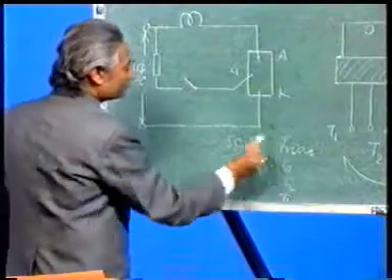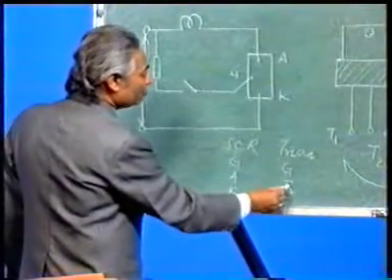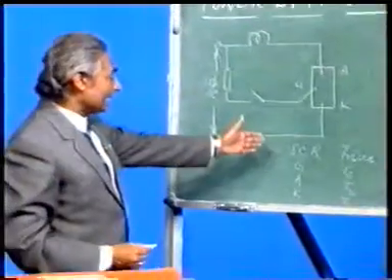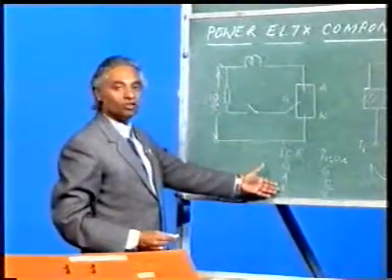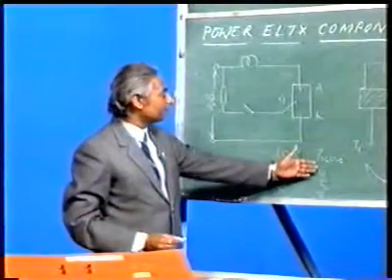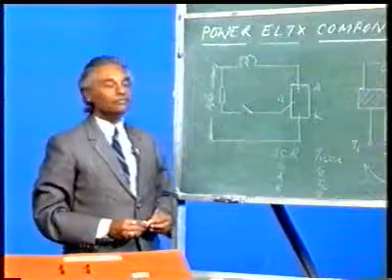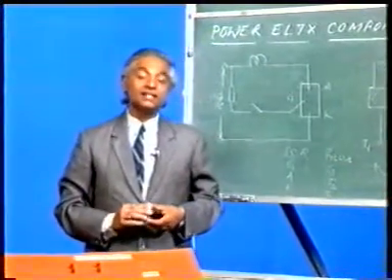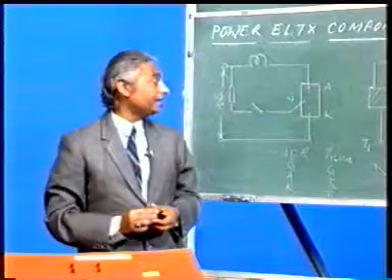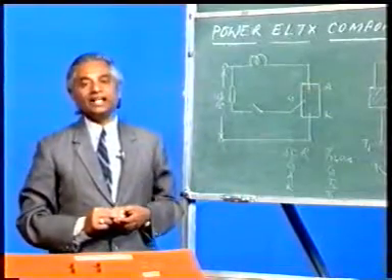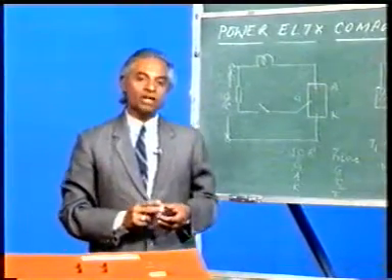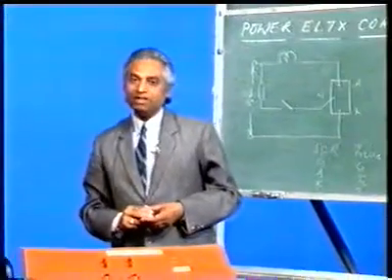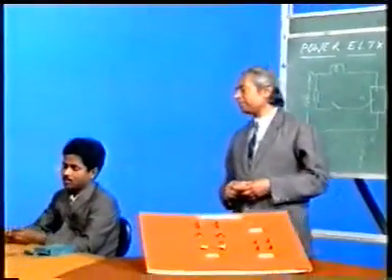So G stands for G, A is replaced by T2 and K is replaced by T1. There I was checking resistance between G and K all the time. Here I will check resistance between G and T1. If the resistance is shown 0, that means it is short. If the resistance is very, very high, say infinite, it is open. So like that we can test it with the help of a multimeter. Again I will request Mr. Singh to demonstrate them on a digital multimeter.